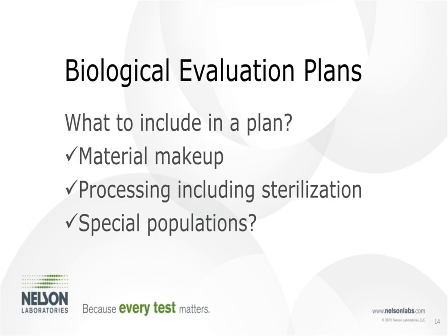adequate material review. I do also want to say here there are things out there like medical grade, USP Class 6, non-cytotoxic, all these things you can get on these materials that you can include in the plans. But don't be fooled. Become educated on what this really means. Material grade, as of right now, there is no criteria around what is called medical grade. I've seen medical grade material that have had all the biocompatibility done on the material, and I've seen medical grade material where only it has a dedicated line that only that material be made, but no testing was done.